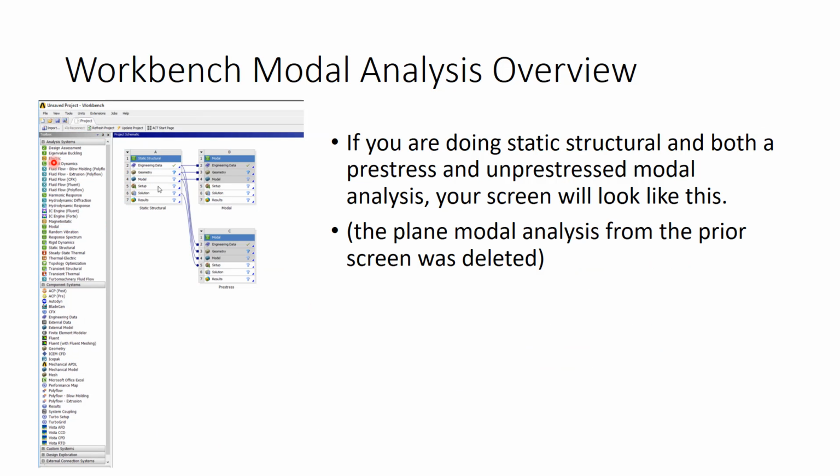So it'll include that initial pre-stress. Okay. So if I were to do both, so I have a static structural and I have this one, you can see it's connected to the model but not to the solution, then this modal up here would not include pre-stress effects. And this one is connected to solution, and so this one would include the pre-stress effects. You could also do that all with just this one by solving for a case where the stress is really low. This static structural up here could be used for looking at the static stress to see if it would fail under static conditions.